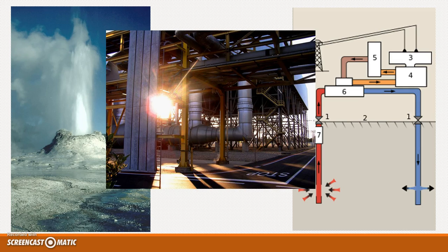In specific cases, there are ranges of EGS resource types and applications. Electricity generation using EGS with fluids from sedimentary and basement rock formations and similar reservoirs. Electricity generation from co-produced oil and gas operations using organic binary power plants. Combined heat and power: cogeneration of electricity and thermal energy.